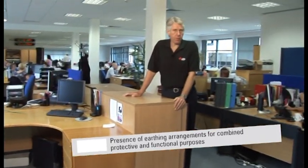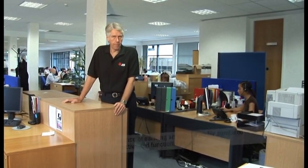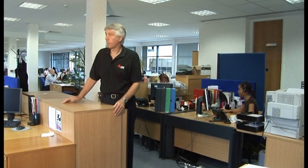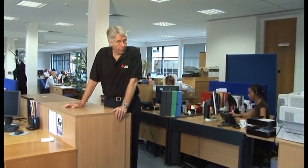Next, we have the presence of earthing arrangements for combined protective and functional purposes. In a situation where a designer knows the intended use of a building, for example in an office, it's easy to predict that there could possibly be a large number of devices, such as PCs, which produce protective conductor currents on the earthing system for functional purposes, usually power supply smoothing and interference suppression. So the protective earthing installed for safety purposes, by default, also acts as a functional earth.